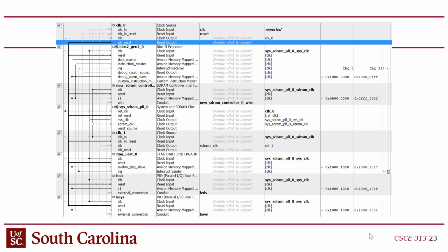GPIO connections. So they allow us to basically go from Avalon to pins, right? What these GPIOs do is they're a bridge. They allow you to do an Avalon read or write transaction over the Avalon bus, so they have a programmed I/O address associated with them, but then they allow you to go straight to pins, right? So these GPIOs are kind of the purest form of software hardware interfacing, because Avalon means load and store instructions, right? Because it's programmed I/O, and then you go straight to pins. And that's the purpose of these guys, to bridge between the I/O instructions and the actual pins, hardware wires.